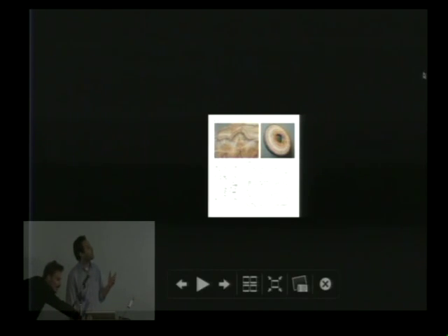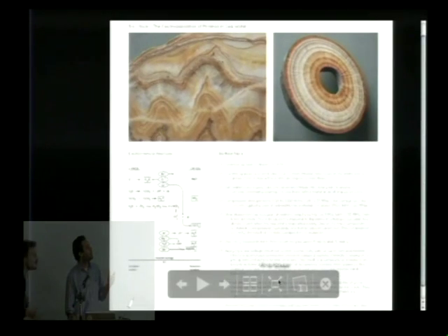This series of cells was used in order to look at a material called biorock, and how biorock accretes around a galvanized steel bar that has electric current passing through it. What was interesting to me was the rate at which it grows, which is roughly 50 millimeters a year, and that can depend on salinity and amount of current. It doesn't need much current, between 5 and 15 watts, and it has the compression strength of concrete.